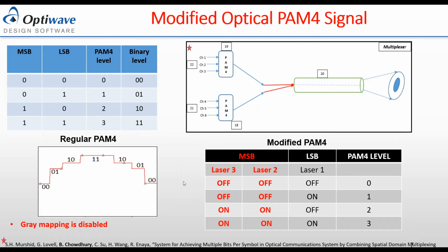But if you go into silicon photonics, as Intel has shown now, these laser diodes could be integrated directly onto the substrate or wafer level. If we have integrated the laser diode directly at the wafer, then we are talking about very inexpensive $1 or $2 laser diodes, even probably less than that, could be integrated. And if you put them in series, the total power addition is significantly lower. It may be adding another 10-15% as opposed to another 100% to make the total power go to 200.